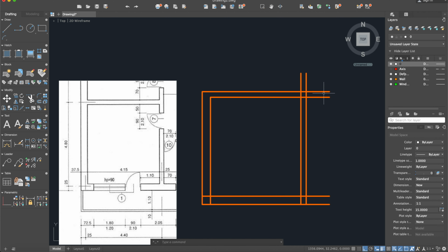Yes. And now I will use the fillet command this time. So fillet, then R for radius. As can be seen here, I must choose between polyline, radius, trim, and multiple. Okay, so R, and I will type the radius to be 0 to have a straight angle. Select this line and this line. It's so important, because if I select this part, it will build a different line and angle here, and I want it to be here. Okay, again, fillet, radius 0.